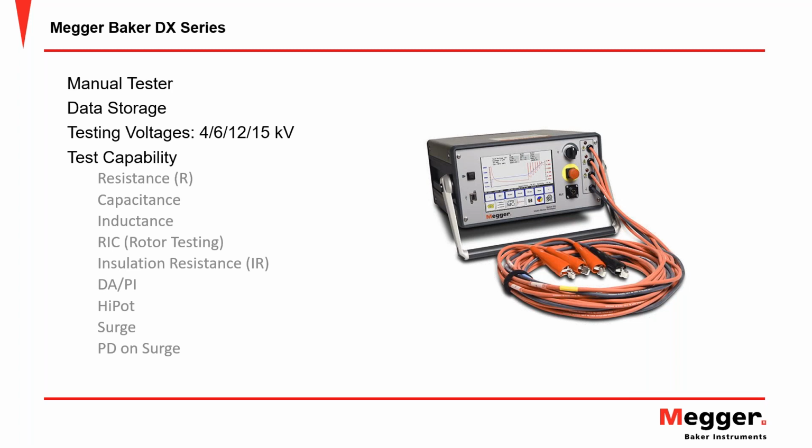The DX series is a manual tester, so you're pushing the button and ramping the voltage. Does have data storage in it, testing voltages 4, 6, 12, and 15 kV, and has a bigger range of test capabilities, so resistance, capacitance, inductance. It will do a rotor influence check, insulation resistance, DA, PI, high pot, and surge, and we also added PD on surge, where we'll take the high frequency content off the surge waveform and quantify that in millivolts to ascertain whether or not you have PD activity in a motor.